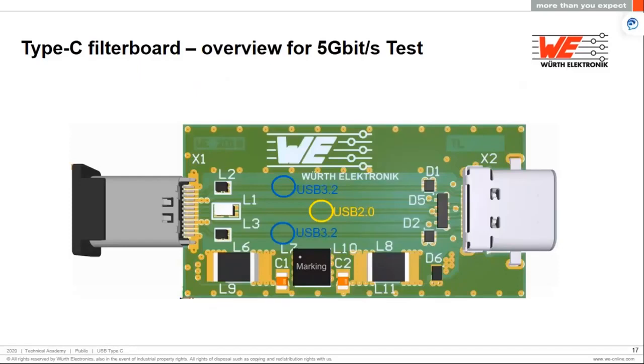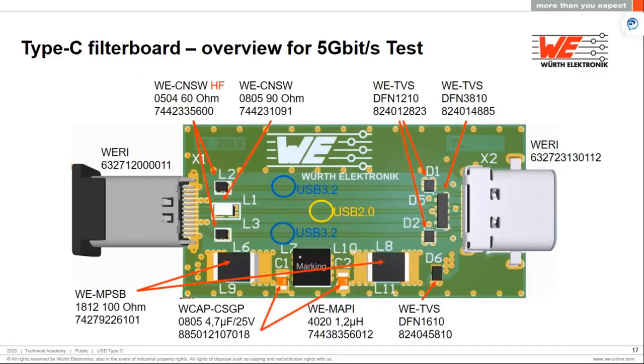Here in this slide, we can see the overview of the dongle and what type of components are used within these dongles. The yellow one we have for low speed lines and control signal here, and the blue one is for high speed such as USB 3.0. And at the bottom, we have 100-watt power path with 20 volts and 5 amps.